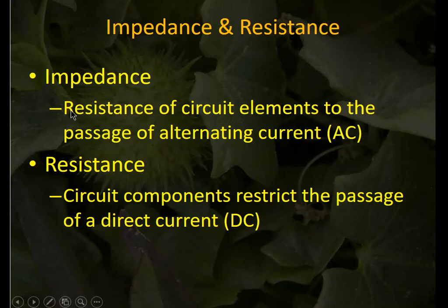So we use impedance where we're already starting out with an alternating current, where we alternate the direction of the current going through, sometimes positive, sometimes negative, alternating every 10 times per second, a 10 hertz alternating current signal. That keeps the circuit elements from polarizing or becoming aligned in one direction only. So that's the difference between impedance and resistance. Impedance is using an alternating current, resistance uses a direct current.